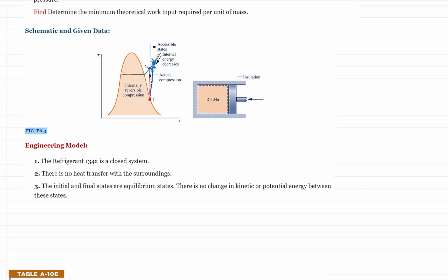We apply the energy balance to determine the minimum theoretical work. It is an adiabatic process. The system is stationary. Divide the equation by mass.